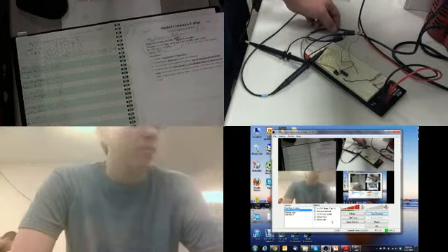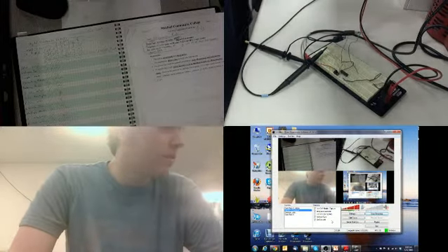Guys, you know what? I didn't realize that these function generators have a CMOS level knob, and I would turn that down to 5 volts because he's up on 7. So this function generator, this big thing that you're going to get your clock out of, has a CMOS level. I would turn that thing down to 5. You have to adjust it with your scope. You have to look at your scope.